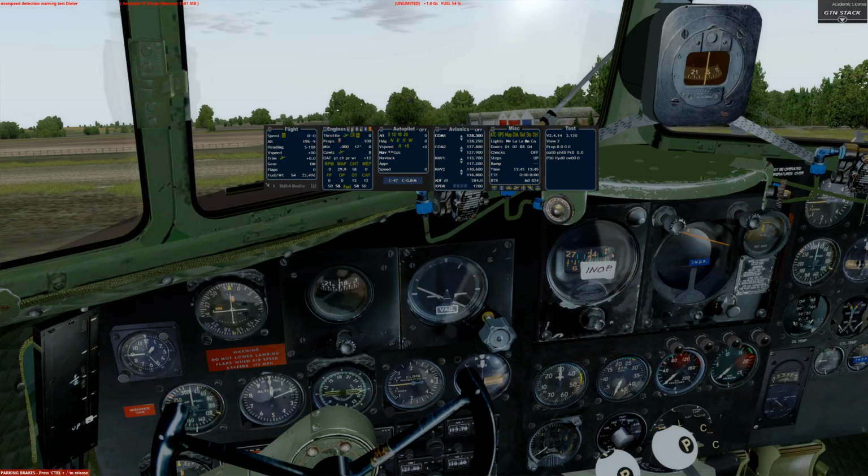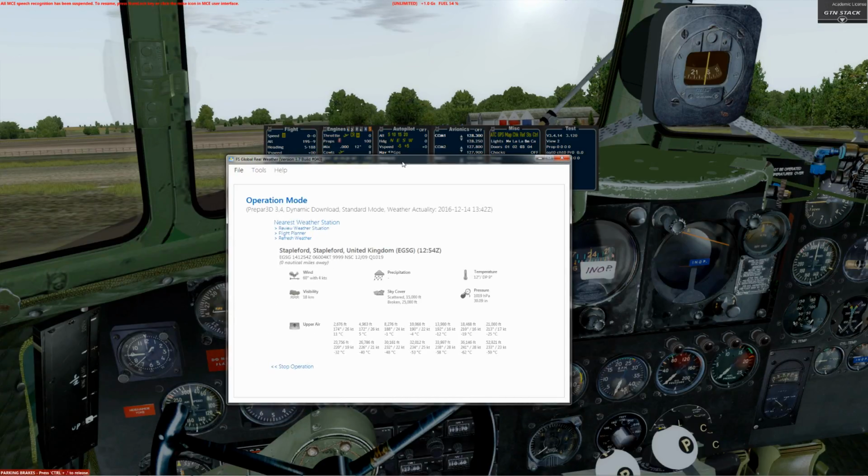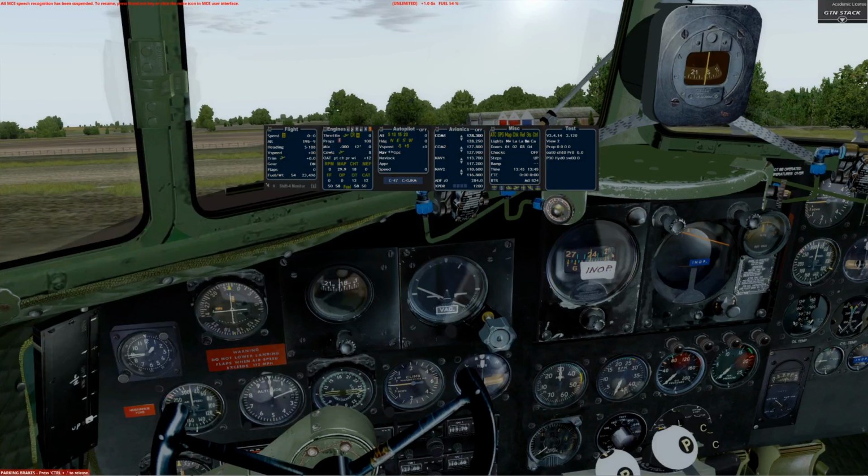Excuse me, that's multi-crew experience running in the background. Our altitude, click to set barometric pressure, currently at 30.09. That is absolutely spot on as per FS Global Real World Weather, 3009 or 1019 hectopascals. Gives our altitude, that is absolutely spot on, 195 feet. The altitude at Stapleford Abbots is 195 feet. Perfect. Heading, our current heading is 188, and it even has south to remind us.